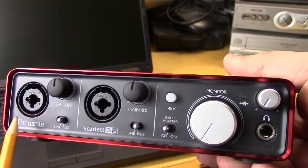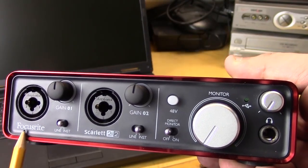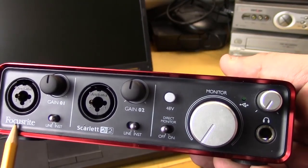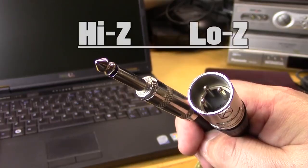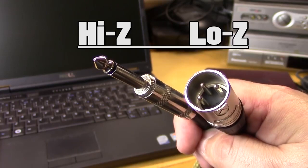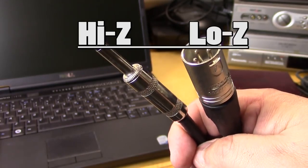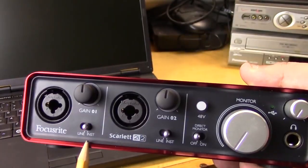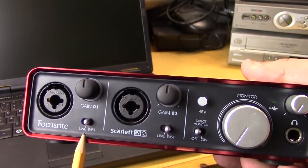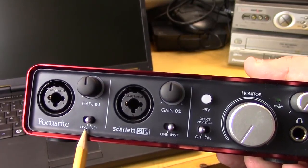Let's take a quick look at the Focusrite. On the front, there are 2 input jacks. Each jack can handle both low impedance and high impedance signals. High impedance looks like the standard jack that we are all familiar with. The low impedance signal is like the standard mic jack that we all know. The mic jack has the benefit of being balanced, which means it can cancel its own noise. There's also a switch to go between line and instrument. If you're plugging in a mic or a line, set it to line. If you're plugging in a guitar, set it to instrument.